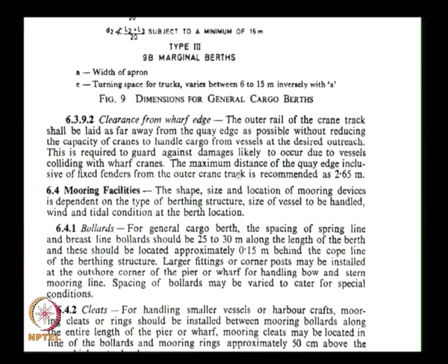But the minimum distance also should be of this order only, because otherwise the vessel will hit the crane. So this 2.65 meter they have given as maximum distance, but the maximum distance is nowadays increased, even up to 3.5 meter they are giving, but minimum distance should be about 2.65 meters. Then this is about the fixing of the rail on the wharf.